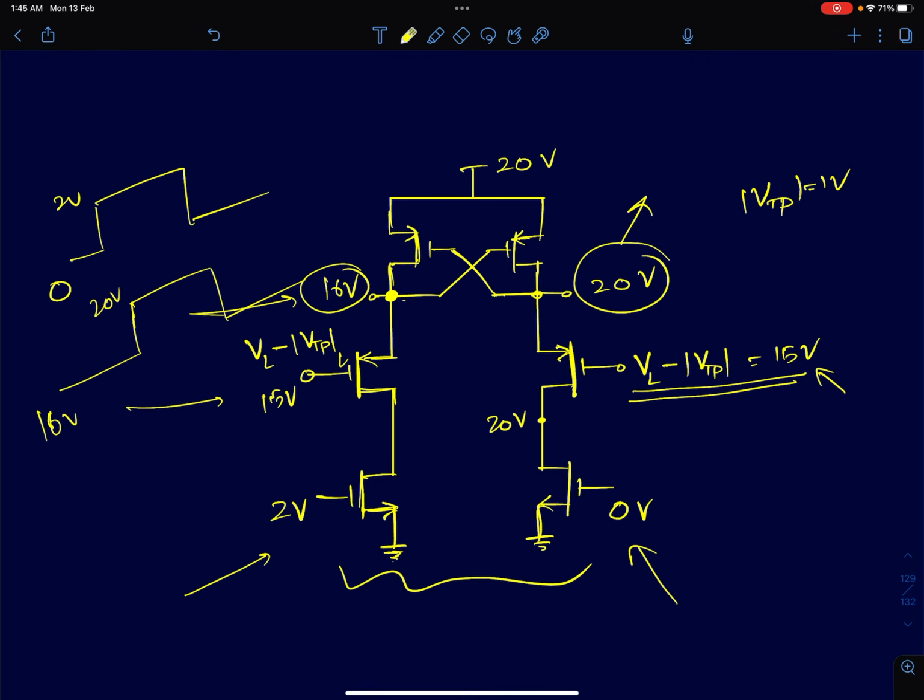So once a CMOS latch regenerates, the only problem you have to worry about is that if any device is conducting by adding this PMOS. Again, that's just to verify static power dissipation being 0. So immediately you can see what happens to the cross-coupled latch. This VGS is 0, so this is cut off. The other PMOS has a full VGS, but its VDS is 0, so that is also cut off. Okay, so since the PMOS upper path is cut off, you can automatically see that there is no static power, there is no path from supply to ground.